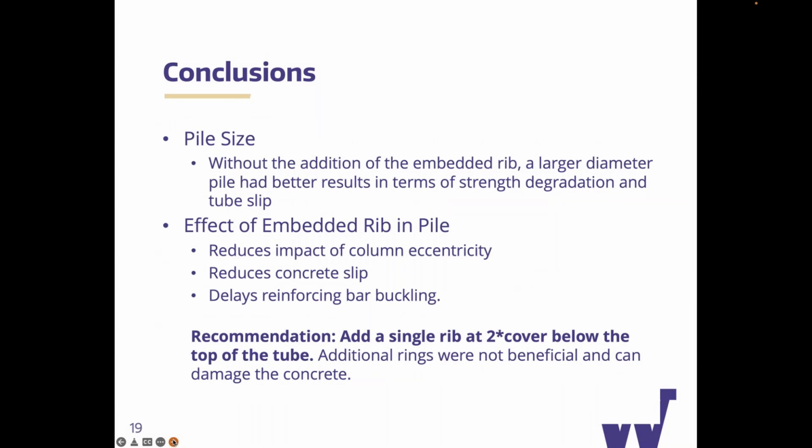The other thing I think is that pile size is important. If you don't add an embedded ring, you're going to get better behavior and less damage if you have a larger diameter pile. So again, we had a column diameter of 20 inches and a pile diameter of 48 inches. That's more than twice the diameter of the column.